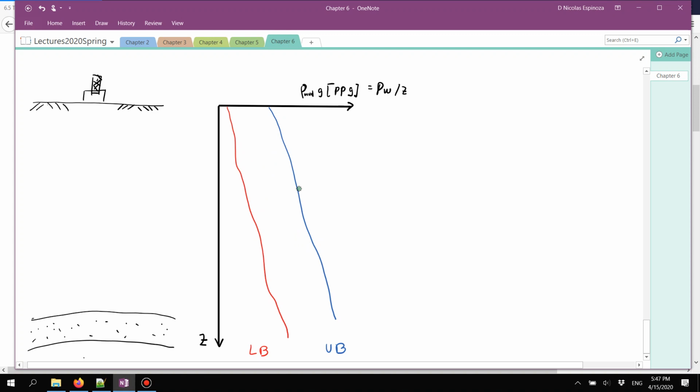So in this case, the best solution will be to start at the highest density which is allowable on surface and go with a constant density mud up to a depth in which that's not possible anymore, and I hit the lower bound.